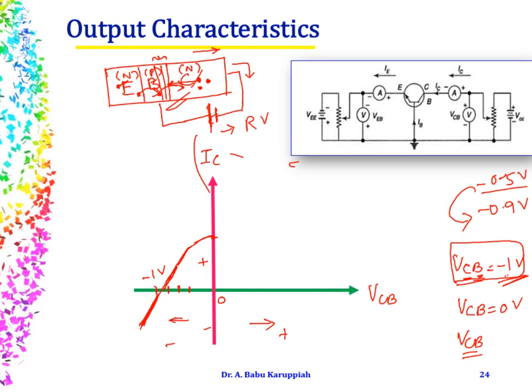These are concepts that we have already seen. So if there are 10 electrons present when you set up the fixed emitter current, these 10 electrons would start flowing inside, and even if you increase your collector base voltage, that will not have any effect on the number of electrons coming inside. These 10 electrons would come into the collector at a constant rate. That is going to be fixed, so you will have a flat curve.